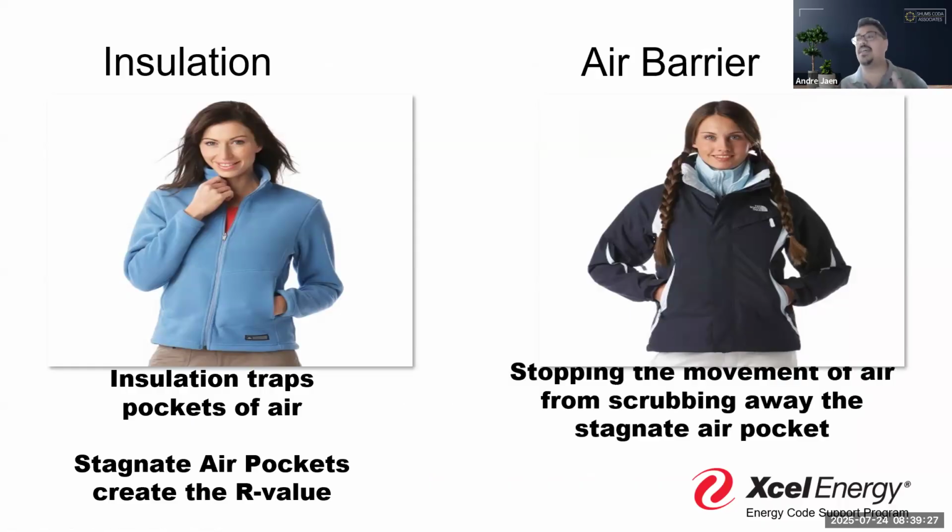And what I really want to point out, because I think this parka example is perfect, and I'll explain why. So you look at her jacket, and I want you to think about like the nice parka or winter jacket that you have at your house, right? That you might pull out here in a few months. And it's got all these little features that we take for granted, right? It's got the little Velcro around the sleeves that you can tie up around your glove. And that makes you're using multiple materials, right? You're using Velcro and the jacket itself to create continuity of the assembly in a place where you have a joint. You have dissimilar materials, right? That is a perfect example of thinking about an air barrier. It has a little flap with the Velcro over the zipper because, again, we have a joint that we have to protect.